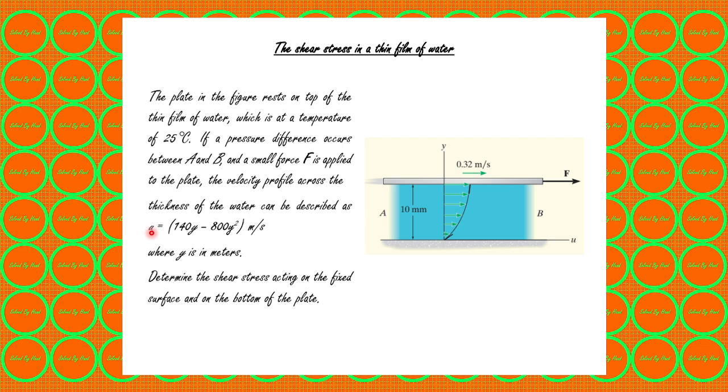In this expression we have u, which is the velocity, and we have y, which is the ordinate, or the vertical distance between the two plates. Here is y, and here u, which is the speed. u is represented by the green arrows, this arrow and this arrow and this arrow and this arrow. If I take the variation of the arrows with respect to the ordinate, it will give me this equation. So I will use this equation.